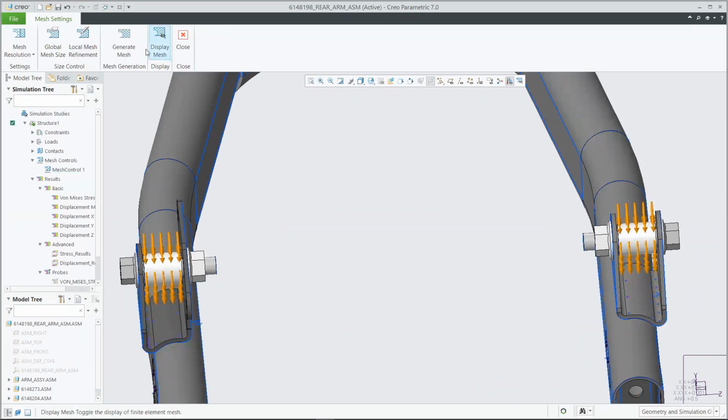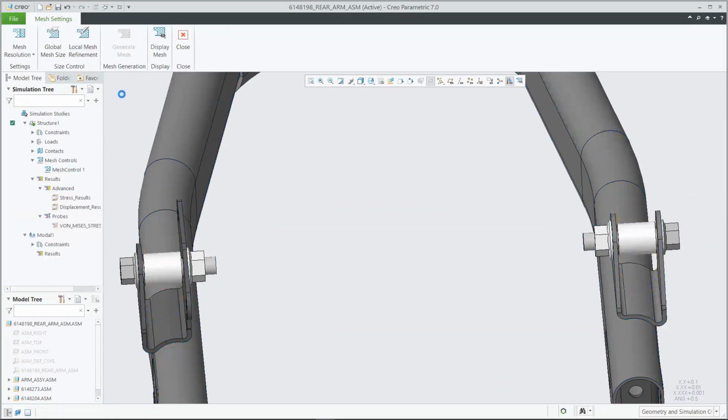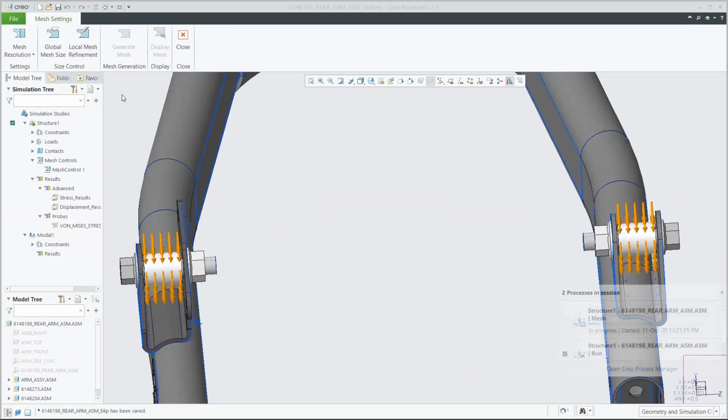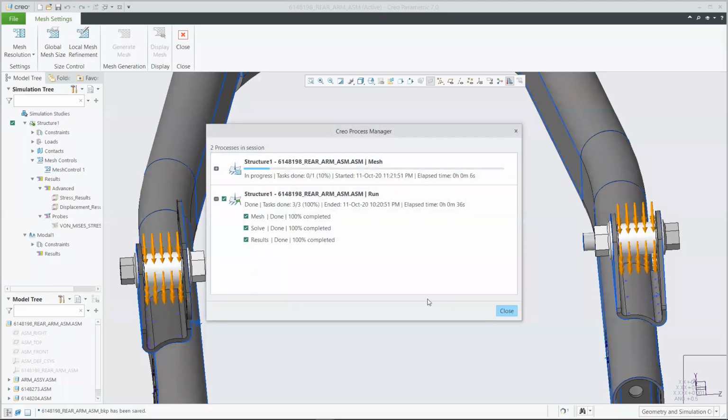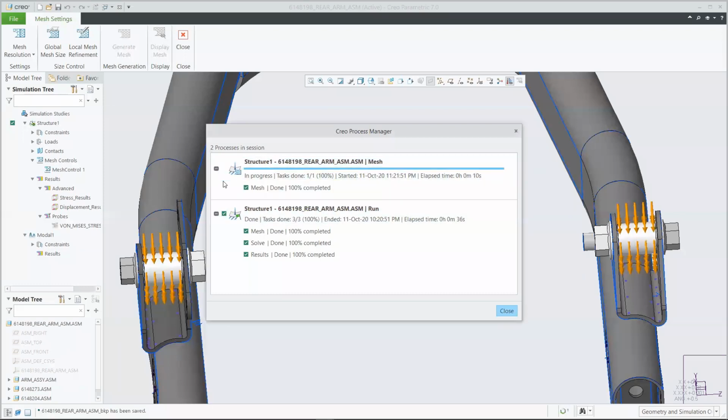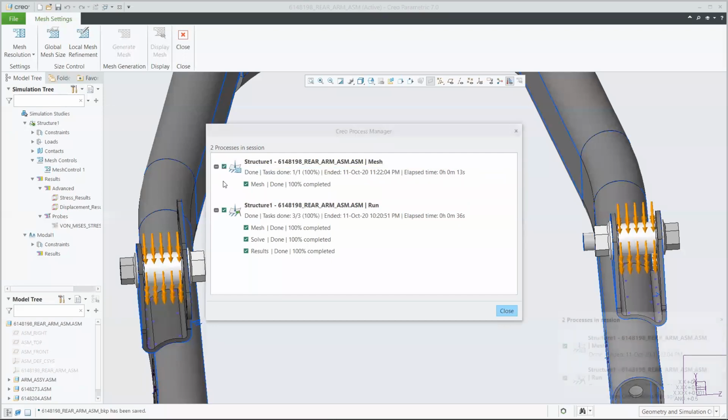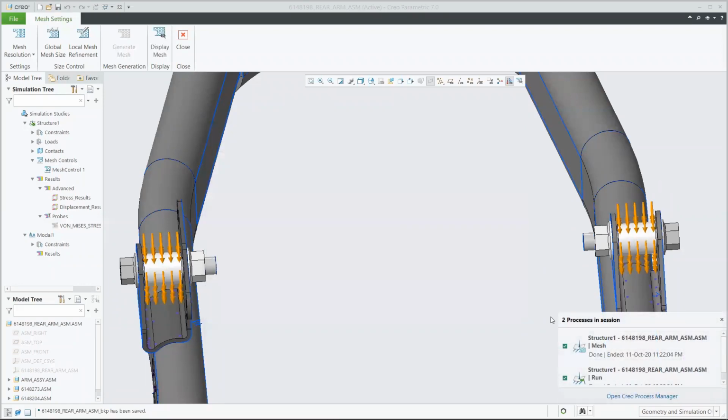If you want high accuracy results in one area, more refined, more calculations per surface area, you don't have to do it to the whole model. You can just run one, see where those high areas of interest are, and then rerun it with a smaller mesh in that area. So again, just some little tips.